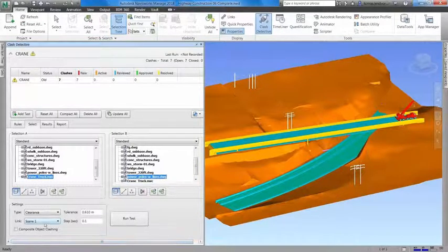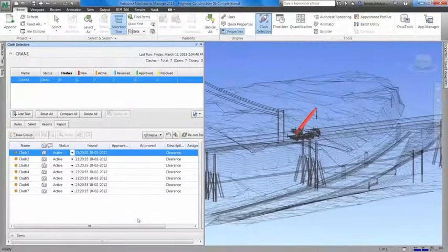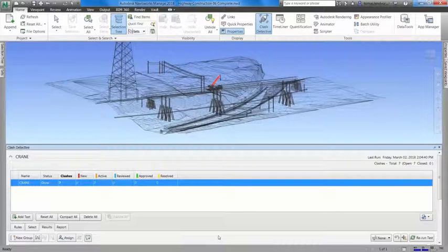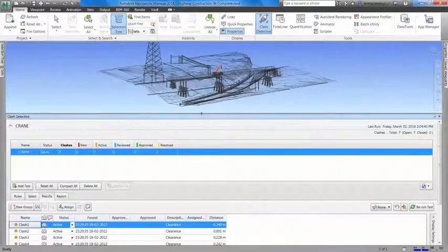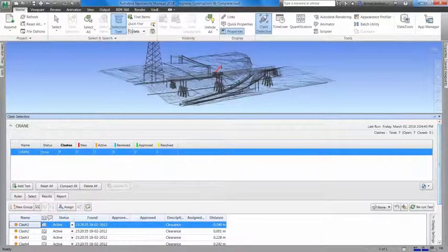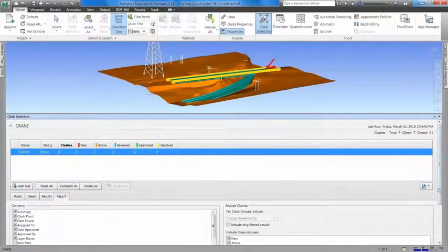So now I will say, okay, show me if there is some clash, and I will even say it's not a hard clash, even if I am 60 centimeters close to the electrical post, just tell me that I am in trouble, and it's telling me. So basically, if the arm is up, the system recognizes that there will be a clash with this electricity, and then obviously we are in trouble. Safety is not very good, so we have to do something about this.